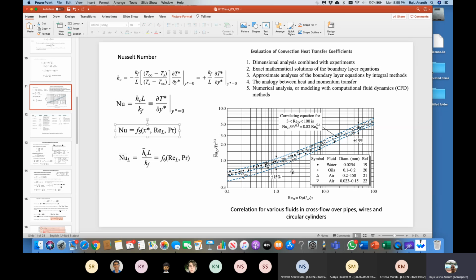It fits very well. That's all I'm showing. So for small ranges, it's a practical range. If I have a chemical flow, maybe the Reynolds number is small, less than 100, I could perform a heat transfer experiment, fit this curve, and use this theoretical or experimental curve to do practical calculations: how much is the heat transfer and so on and so forth.